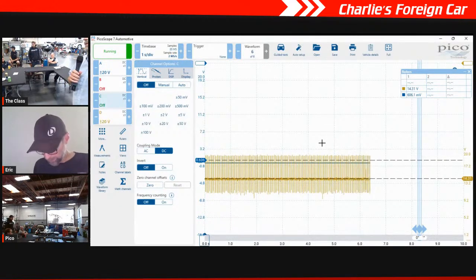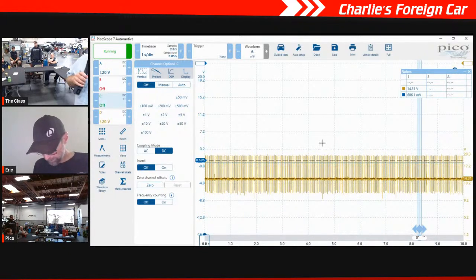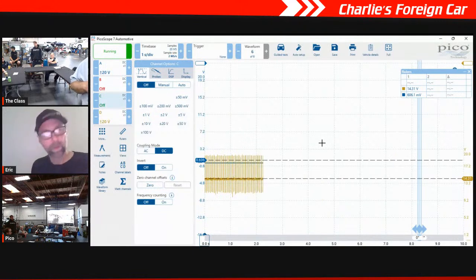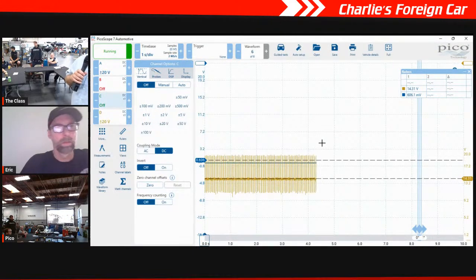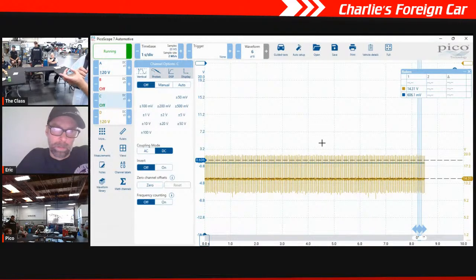That sounds like there's a restriction in that circuit. Either there's a huge restriction, or I'm almost thinking that little ring that holds oil back between the two cam journals, one on each side, is cracked or something, and it's just dumping the oil out of the side of the cam before it can ever get into that solenoid.